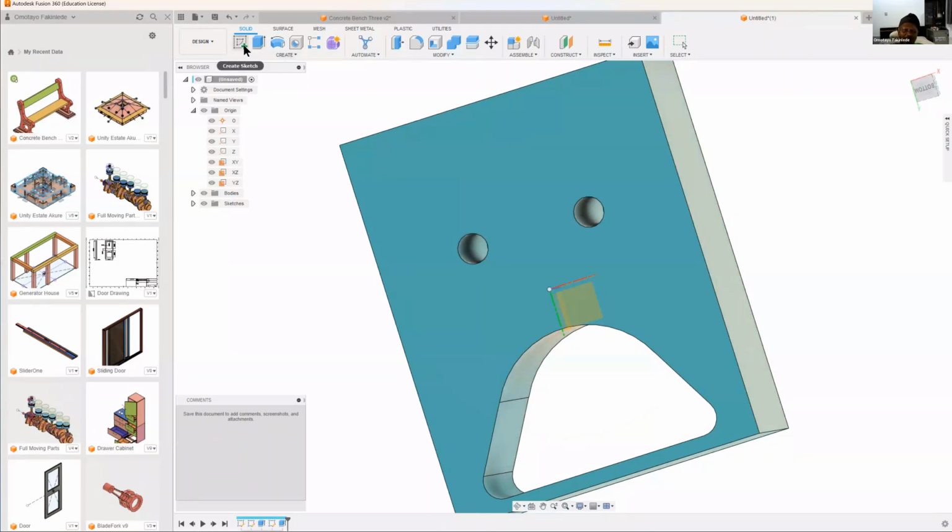You need to just come here and play with it. Let us just look at some of the things I've done. I did sketching by starting with create sketch. If I want to do a sketch, I create sketch. And the first thing I do is select the plane on which I want the sketch to be. From that plane, I can now start putting the sketching elements. They can be circles, lines, splines, rectangles, all those things. And I can then edit them, modify them. I can do several things with them. Those are the kinds of things that are possible with your sketch.